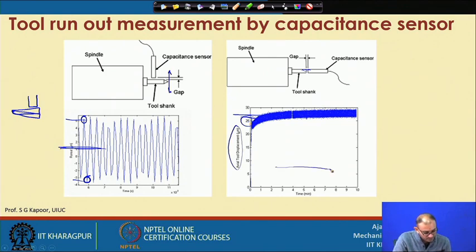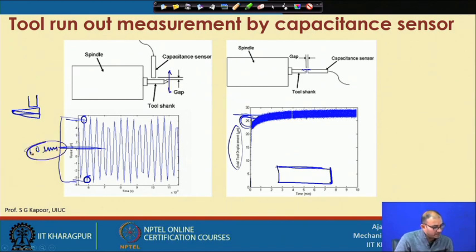Now, if you are machining with this surface, and you have 25 micron axially and something like 5 micron radially at that particular diameter. If you are moving with plus or minus 5 micron, that means you are actually working with a 10 micron range. So, you cannot make any diameter less than the diameter of the actual cutting tool plus this amount. That is not possible here. Other than that, there is a variation in the depth also. You will get a different depth at different locations depending on this particular band. Whatever this band is, that much variation you will get in the Z direction.